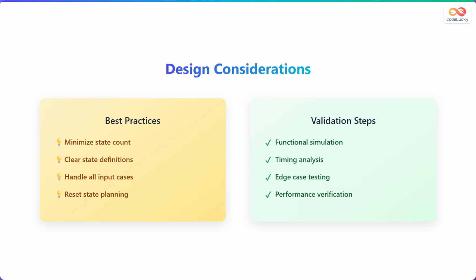Before concluding, let's consider some design practices and validation steps. Follow these best practices. Minimize state count, use clear state definitions, handle all input cases, and plan a reset state. Here are some validation steps: functional simulation, timing analysis, edge case testing, and performance verification.